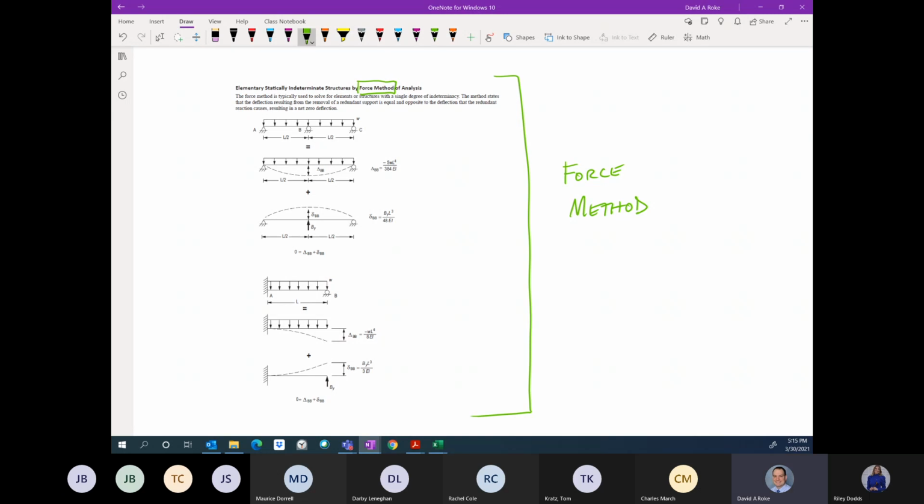So when I look at this structure, they actually provide an example here to demonstrate two different examples to demonstrate this concept. So let's separate those out here. So here's example 1, and here's example 2. So in the first example, our beam has supports at A, B, and C. A is a pin, B is a roller, and C is a roller. We have 4 reactions.